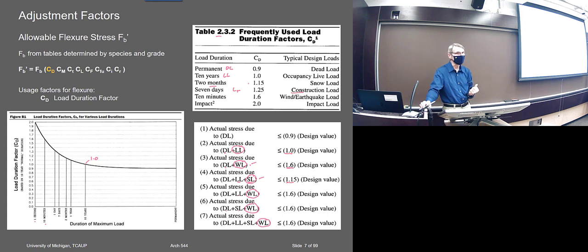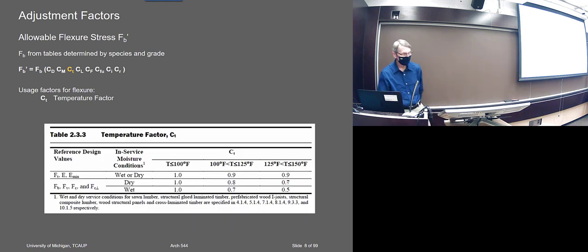That would be your controlling load case. So you've got to consider that in deciding which is the controlling load case. Of course, if you weren't sure, you could just do them all, right, and see which one controlled. But you don't really need to. You can determine it just based on the moment and the CD factors.